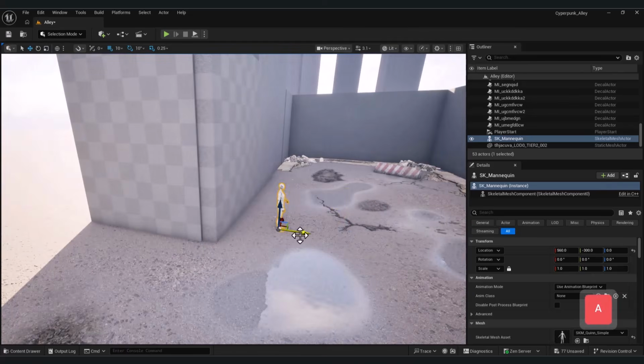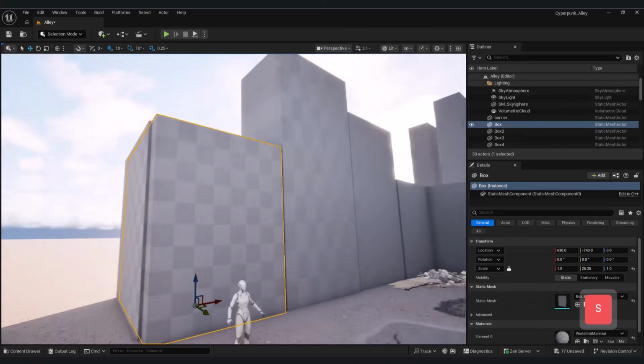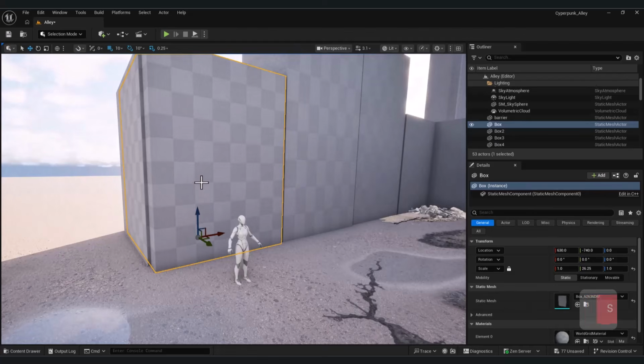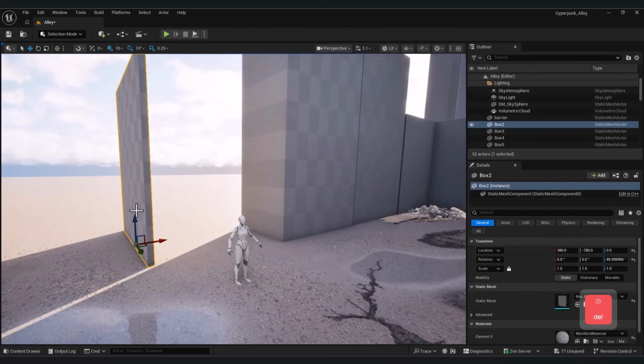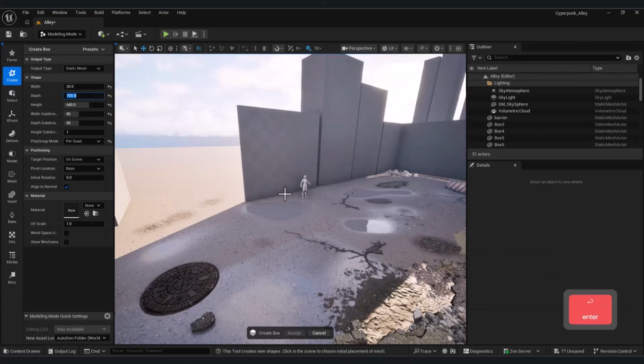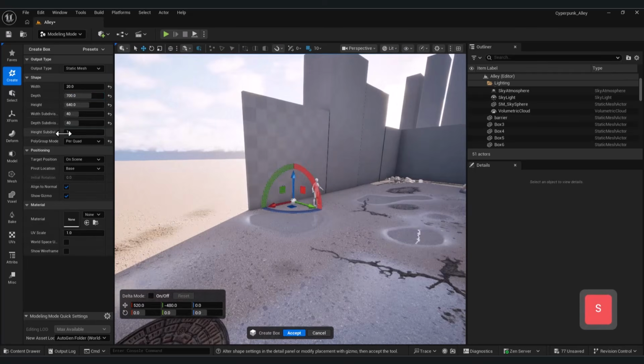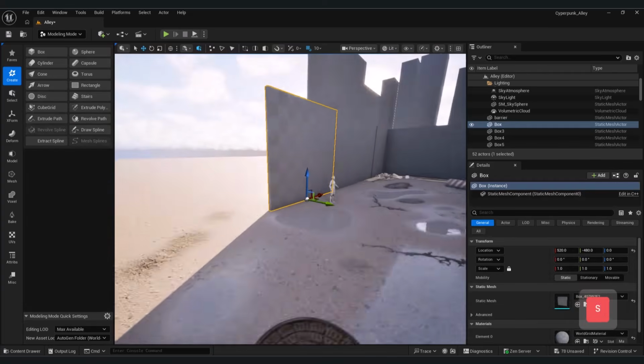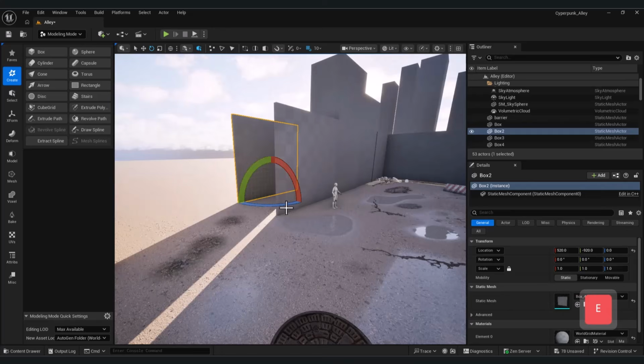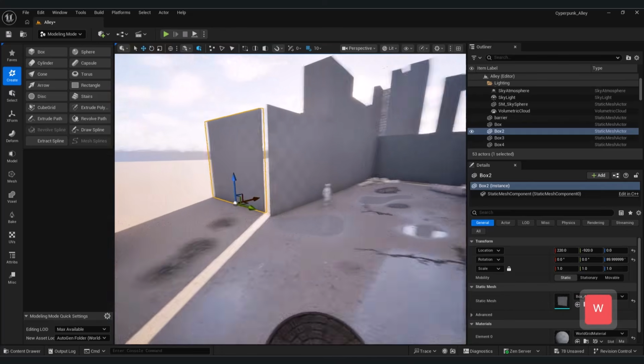In the first method, we want to model the building directly inside Unreal Engine. In this method, I set the building height to 640 centimeters so that each floor is 320 centimeters. However, because there is a shop in the building, the first floor will be a bit higher.